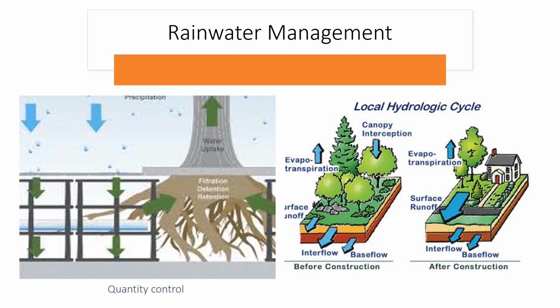Non-point source pollution is pollution from multiple sources that's impossible to identify. Low-impact development manages rainwater by mimicking nature. You can collect and reuse the water for non-potable use, and to replicate the natural balance, you can use low-impact development, or LID, and green infrastructure. You can minimize impervious areas. You can install dry ponds, rain gardens, bioswales to slow runoff, and incorporate rainwater management into site design.